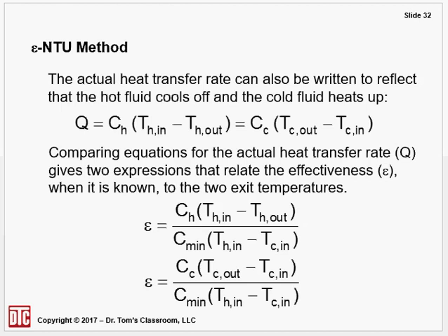The first one, if you look through there, there's N, but then there's T_H out, the second term in the numerator. That's one you don't know. So once you know epsilon, you know everything else. You can solve and come out with T sub H out. We'll do that here in a second, but this is how you rearrange the two formulas.